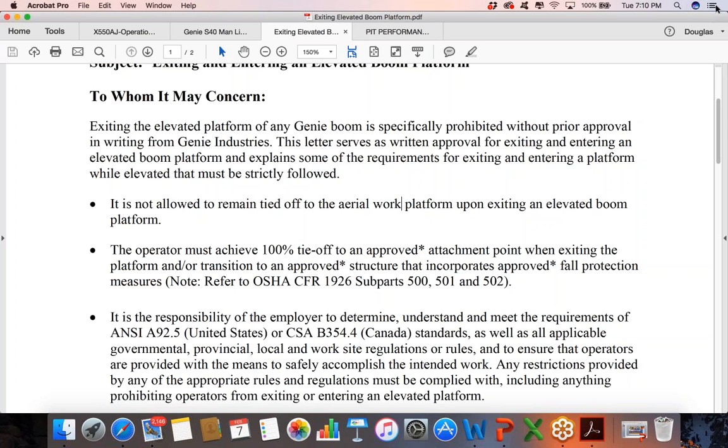It's not going to be practical to put guardrail systems. So we're going to either have to have personal fall arrest, some type of fall restraint system, or some type of safety net in place. Those are going to be the three ways that we can protect an employee with an open edge. Personal fall arrest, so they're going to be in a harness. The ABCDs of fall protection. Anchor points, body harnesses, connectors, and then possibly decelerators in place too, like a shock absorber. So again, ABCDs: anchor points, body harness, connectors, and then decelerators.